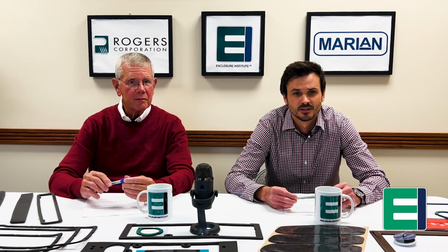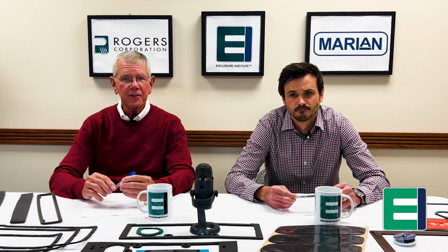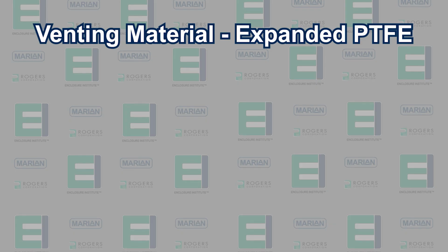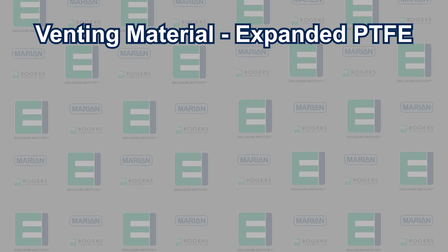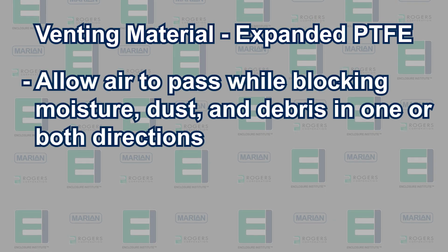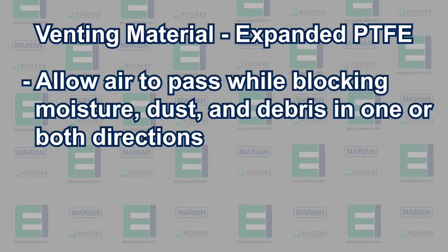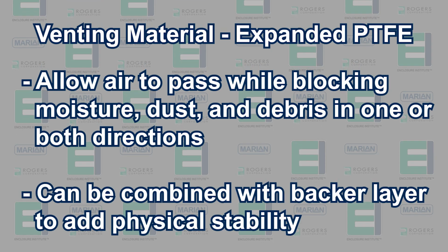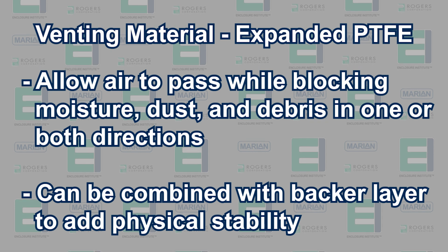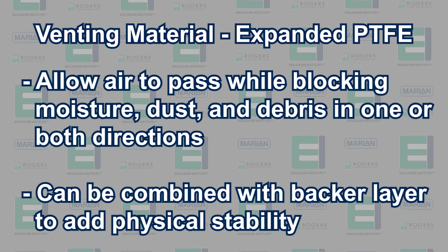It can be installed easily and will bond securely when matched with the right PSA product for the vent film and the enclosure structure. As you might suspect, there are many choices of venting fabrics and films available for breathable vents. Many are made from expanded PTFE membranes, which allow air to pass while blocking moisture, dust, and debris in one direction or both. These ePTFE films can be combined with a backer layer to add physical stability to the extremely thin membrane.